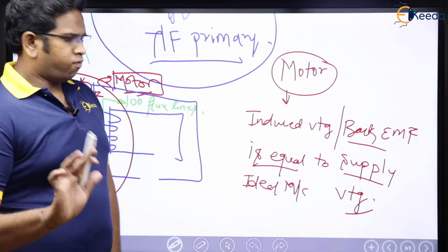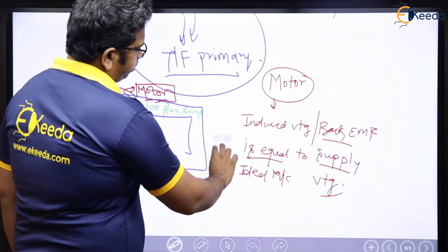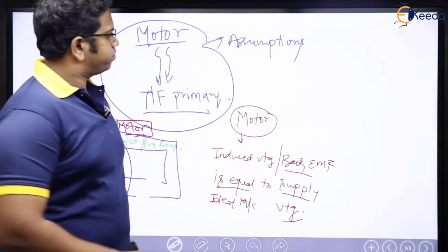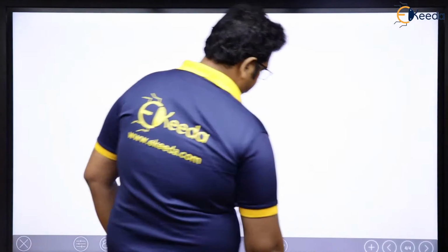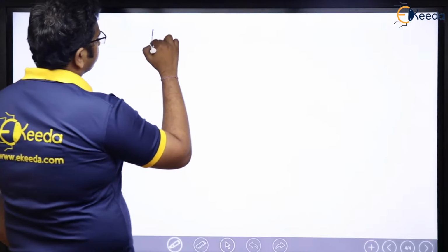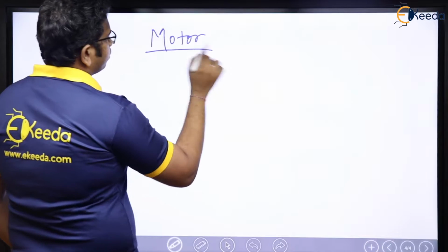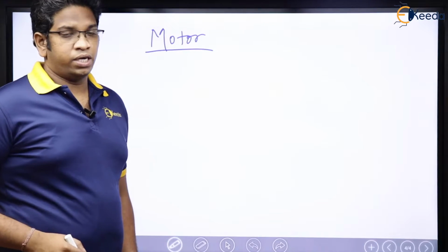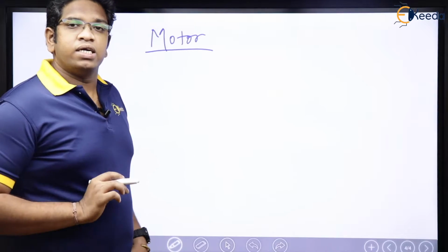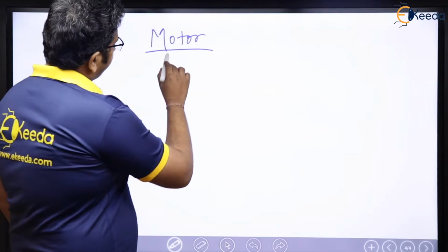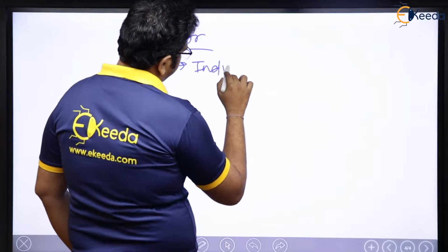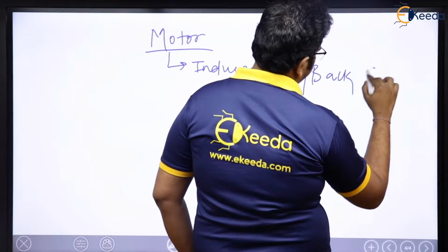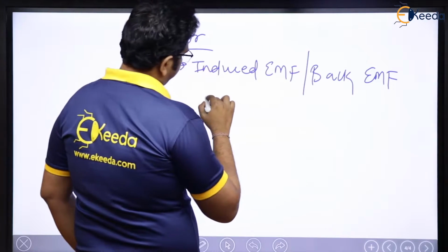Now see here, very important, very easy. When I am saying that in case of motor, induced voltage will not change, I can say that in case of motor, since its input is connected to an ideal voltage source, from the assumptions video we have seen, the back EMF of the motor, or we can say induced EMF, will not change.